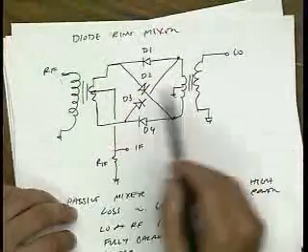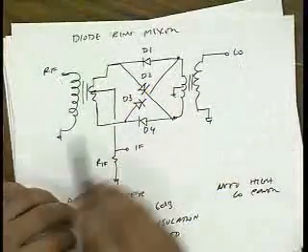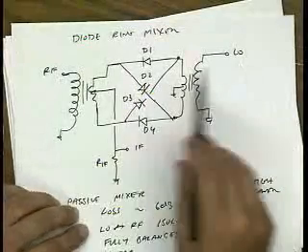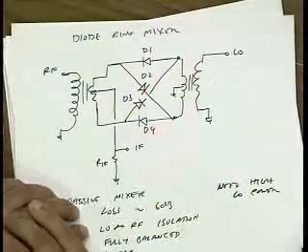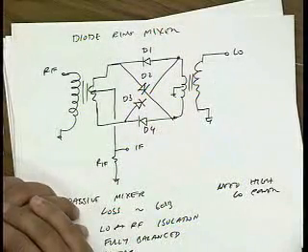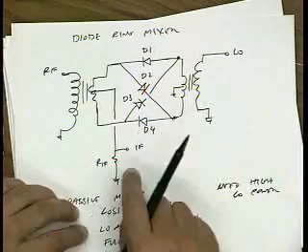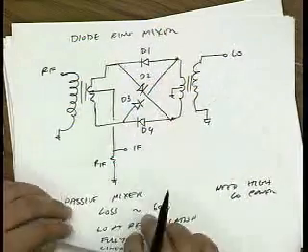Another nice thing here is because I'm using baluns, I can drive my LO either single-ended or fully differential. It doesn't matter. So this is usually sold as a standalone component where you drive the LO and RF port single-ended and you take a single-ended IF signal. It's a nice building block kind of circuit. Let's draw the equivalent circuit in the positive and negative LO cycle.